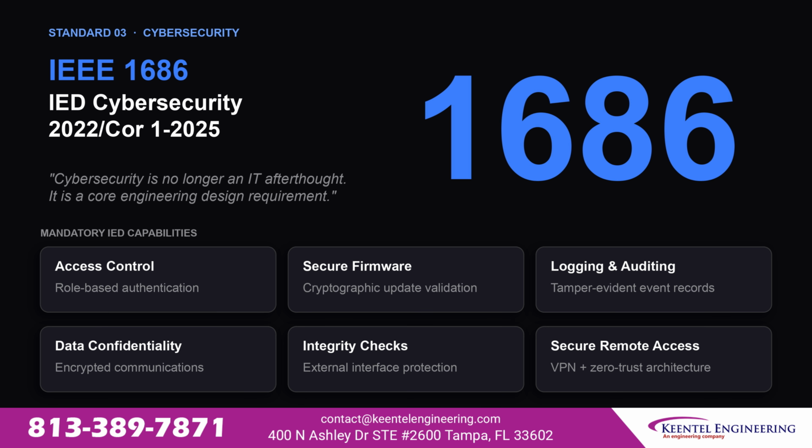Cybersecurity is no longer an IT afterthought. It is a core engineering design requirement. IEEE 1686, updated with a 2025 core addendum, defines mandatory cybersecurity capabilities for every IED deployed in a substation. Role-based access control, cryptographically validated firmware updates, tamper-evident logging and auditing, encrypted communications, integrity checks on all external interfaces, and secure remote access using VPN and zero-trust architecture.